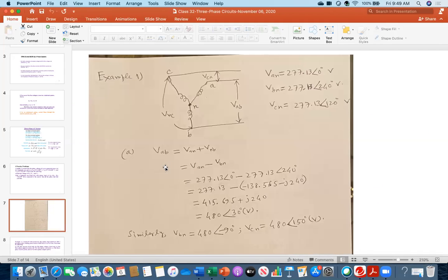So therefore, everybody look how I am solving what I wrote, VAB. Keep in mind that when you are adding AC quantities, because these are given as phasors, and phasor means vector, you have to properly follow the direction as well. That is the definition of a phasor or vector: it has a magnitude and a particular direction, which means phase angle in this case.